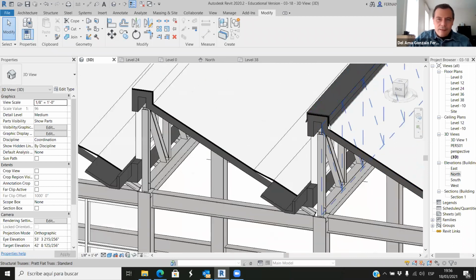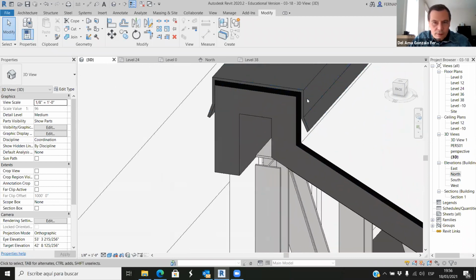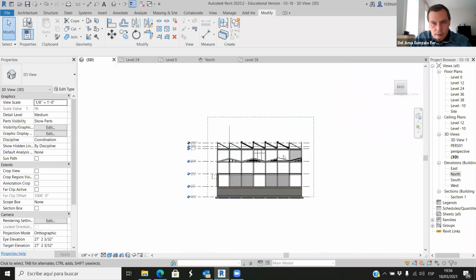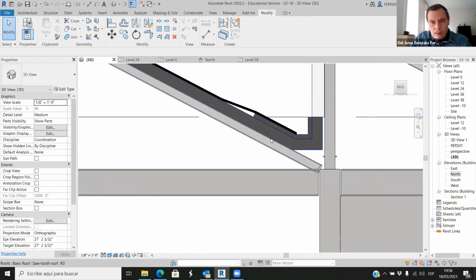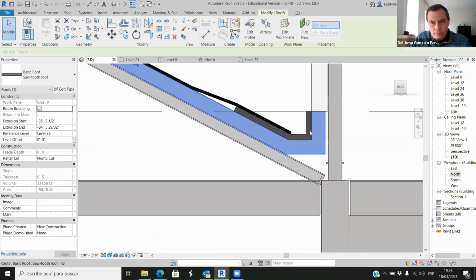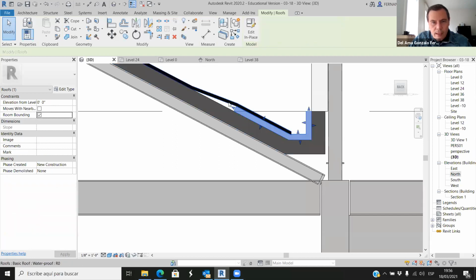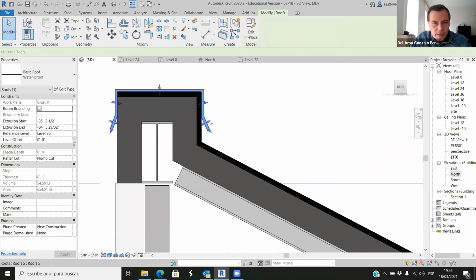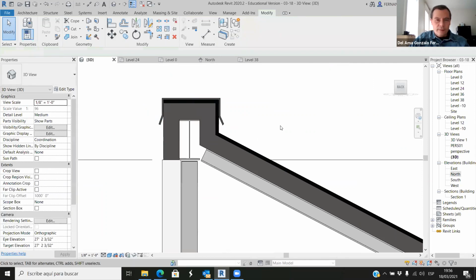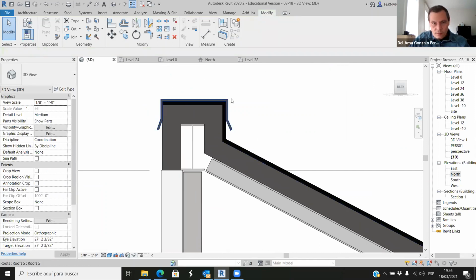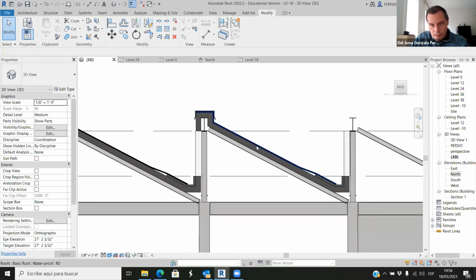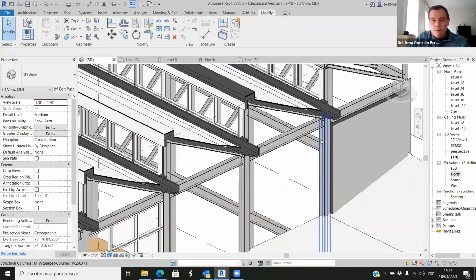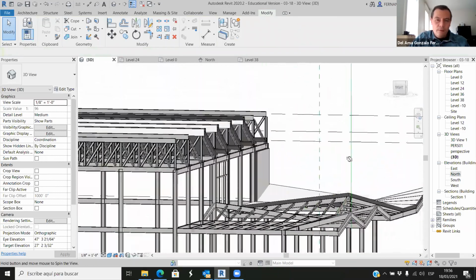So as you can see, this is about protecting things against water and overlapping things. Look at the section. This is the roof. Then I have the gutter. Then I have this element overlapping this. And then finally I have this element overlapping the waterproof layer. Okay, so now I think we are moving the water down and out, down and out, because it goes away out of the building with the gutter.